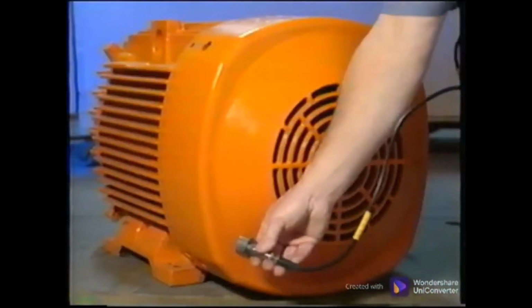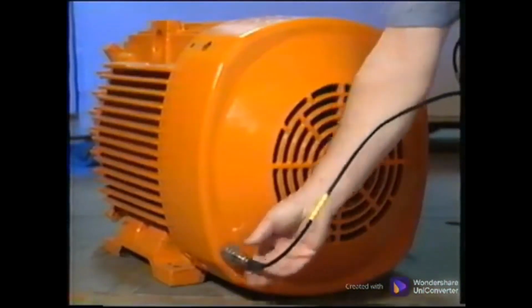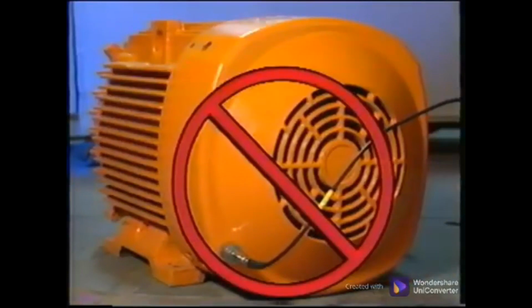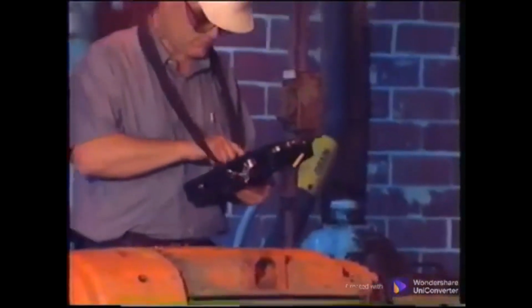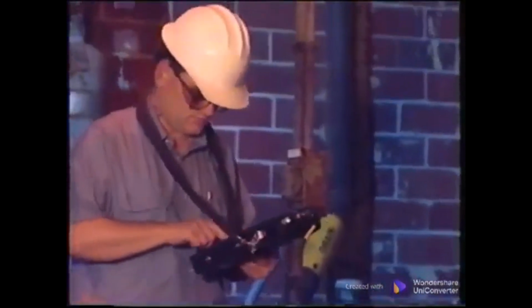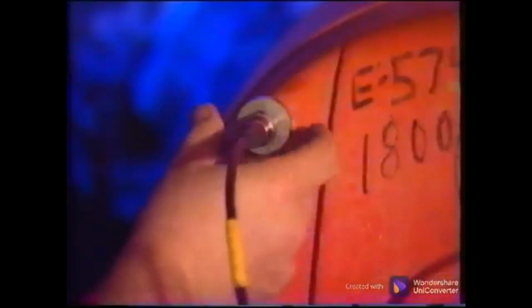The axial measurement on this motor could be made at any of several places. The simplest place is on the end bell at the recommended clock face position, but the same restrictions apply for this axial measurement as for the radial measurements. Don't make measurements on the end bell, as it will only be an accurate indication of the bell's movement, not the machine's movement. If no better place is available, the axial reading could be made on a through bolt that fastens the end bell to a solid part of the motor.